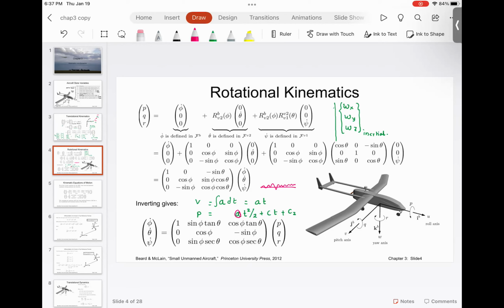So wing deflection and all, we are not talking about control surfaces yet. Right now we are assuming the aircraft is completely rigid. Sensors are noisy, and we use smart sensor fusion algorithms, Kalman filtering, particle filtering, and variations of these filters to minimize the error. Coming back to the point that I was trying to discuss.